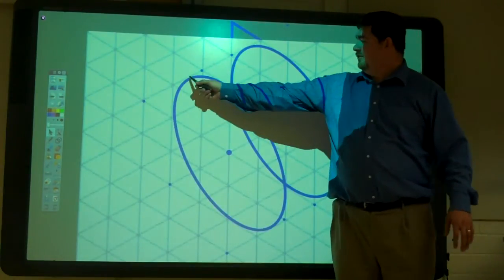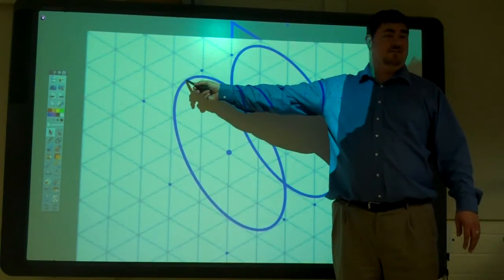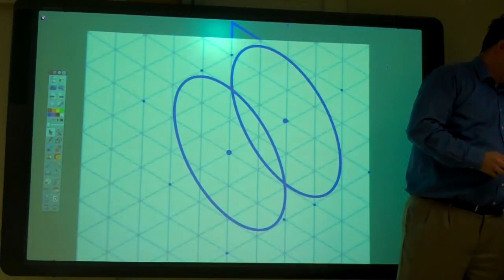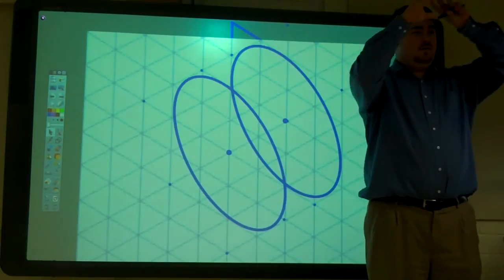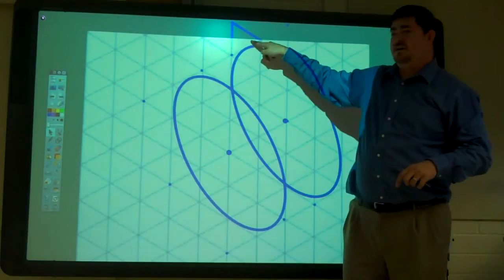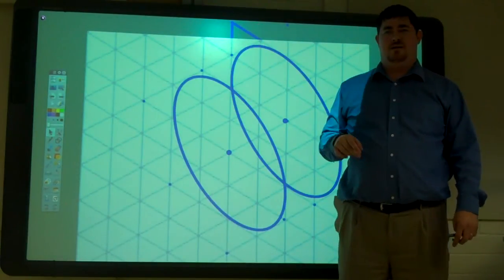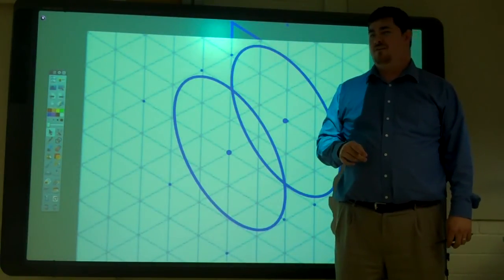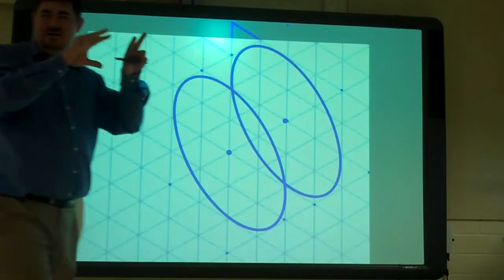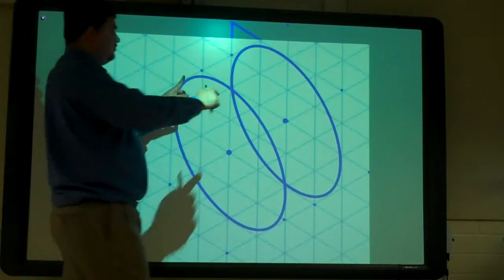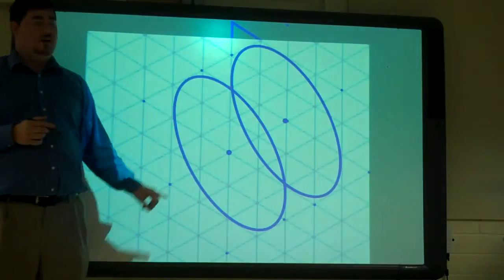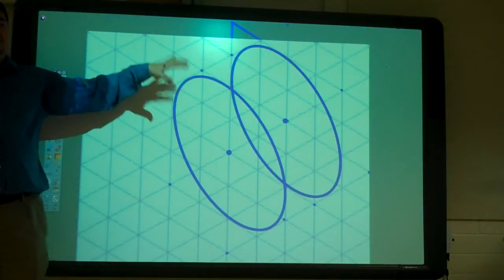That's right along that 30-degree line. It's tangent to both of those, right? Because if I have that cylinder, I'm going to see an edge there, right? So just that 30-degree line right there. What's the best way to make that line? Yeah, put your triangle down. Take your triangle, line it up on those two, draw a line. If you did it right, it should be right on the 30 degrees.